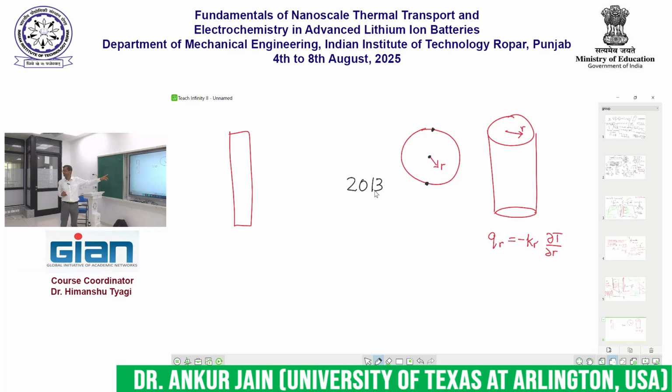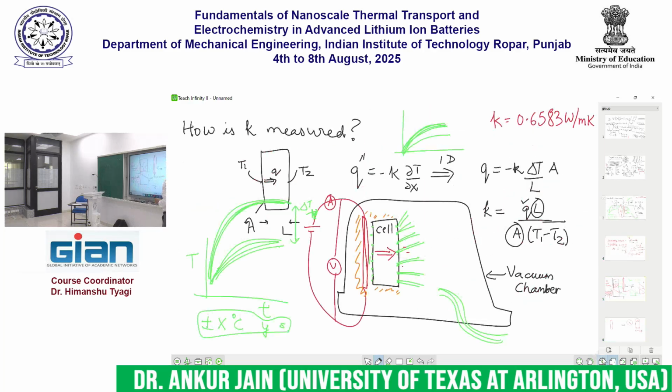In that measurement, we were also interested in measuring the axial thermal conductivity of the cell, because ultimately the interest is in determining if the two thermal conductivities are very different from each other or not. I hope you can see that measuring the axial thermal conductivity of this cell is not that difficult, right? It will in fact be very similar to this prismatic measurement that we've been talking about.